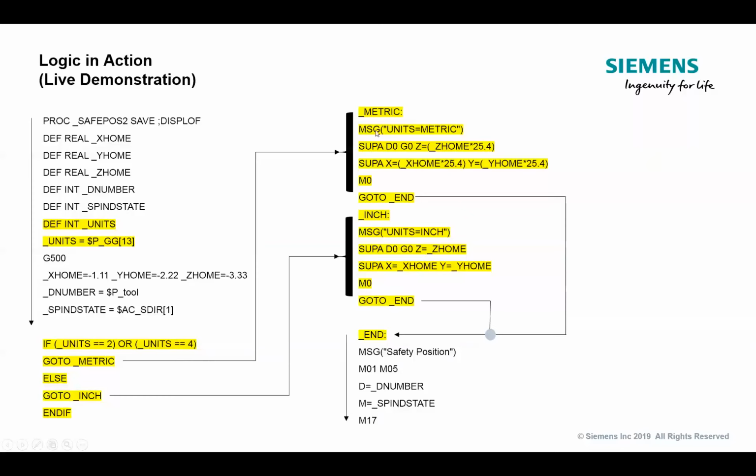And that's what's going to determine where I go within the routine, right? Think of this as you start to look at logic statements. Think of it kind of like water flowing down a river, right? And then it's going to hit a divide. Which way am I going? Those are your if-then statement logics, right? If this condition's true, go to this, and the underscore metric, that's just a label, right? All I did was create a simple label and pointing the system to go there. Or, which is my else statement, go there. And that's allowing me to jump over sections of routines. And then at the end, so I don't run this section of code, I want to do a final jump to a new label and then continue on. So there's a lot of little jumps going on when you get into this conditional logic.